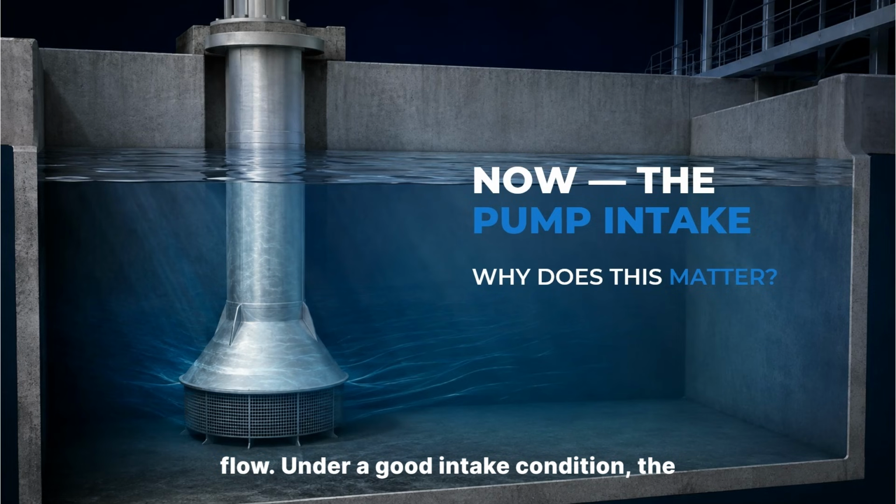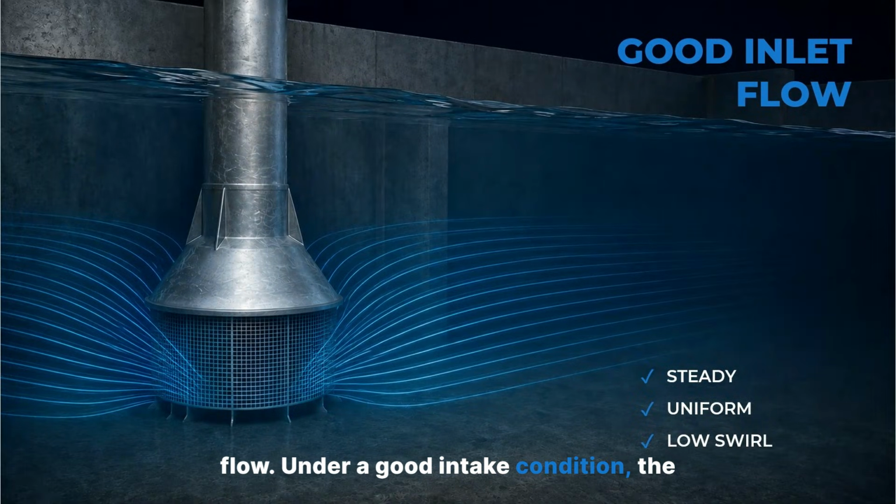Good inlet flow. Under a good intake condition, the incoming liquid should approach the pump in a reasonably controlled way. The flow should be steady. It should be reasonably uniform, and it should contain as little unwanted swirl as practical. This gives the pump a much better inlet condition.